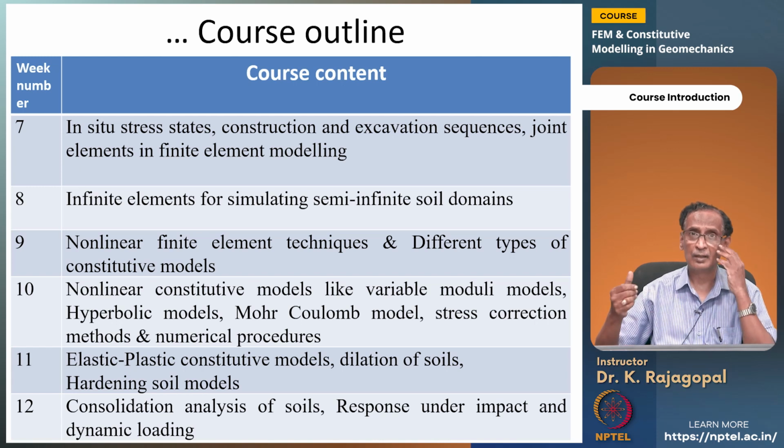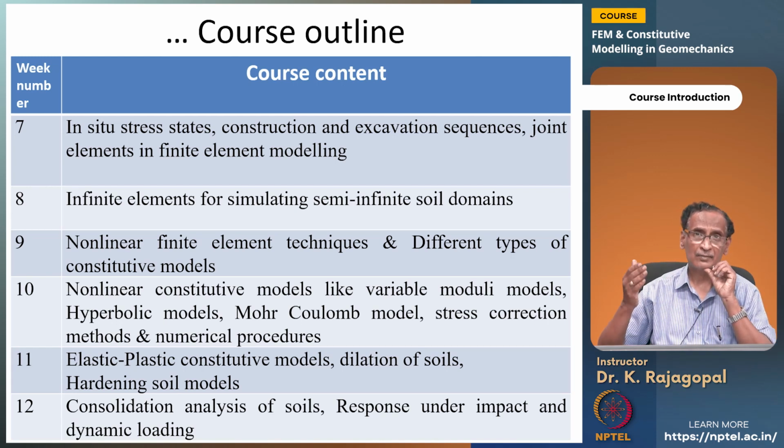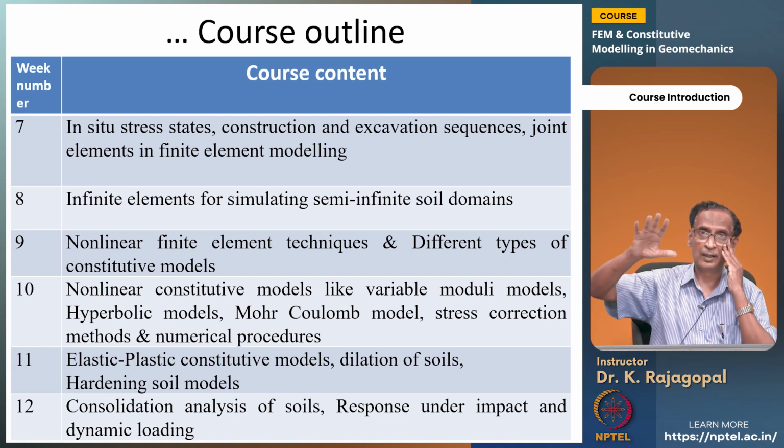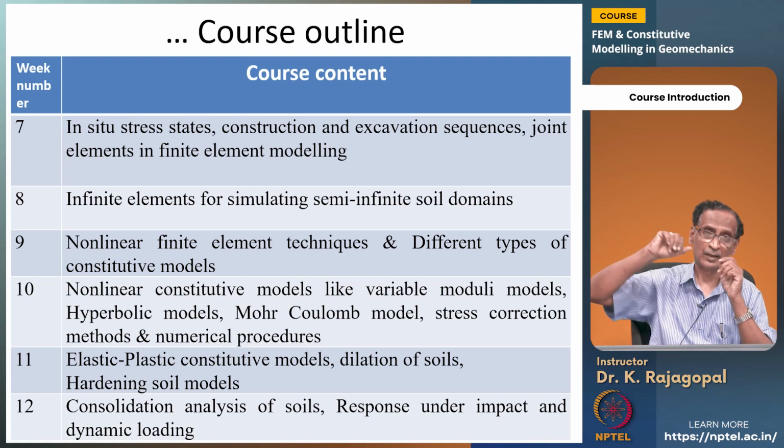Then what are the different stress correction methods, because when we are dealing with any constitutive model, like for example our Mohr-Coulomb model, the tau max is c plus sigma tan phi, or if you draw any Mohr circle, it should be just tangent to our yield surface.